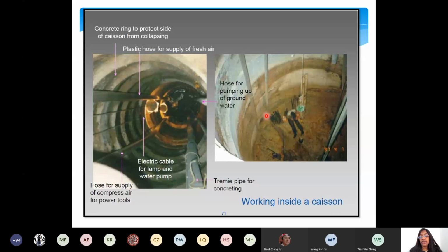Okay, there are chances, when I talk about these caissons, there are a number of accidents due to these caisson type of piles. Have you come across the recent news? Two days before, they built the caisson and finished. The bore is done, the outer layer is done, the skeleton is done. The next day they are supposed to go for piling. It is open, the well is open. If it is not protected properly, there are chances of passers-by and animals falling into the pile. So care should be taken.